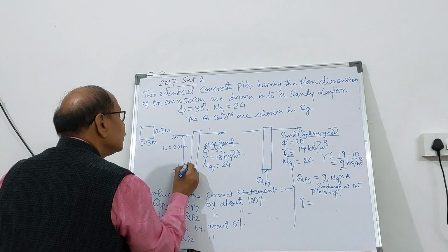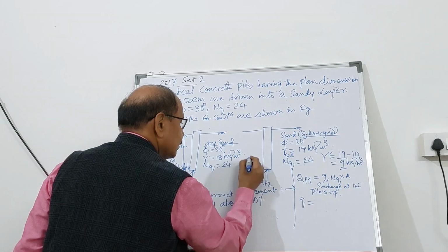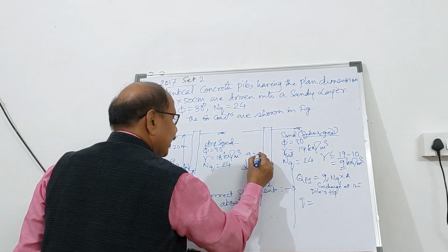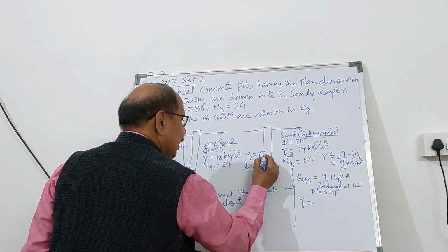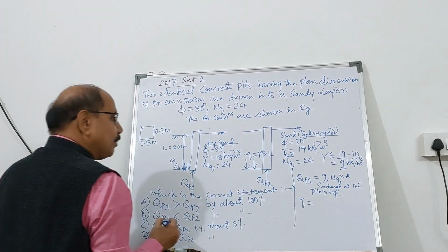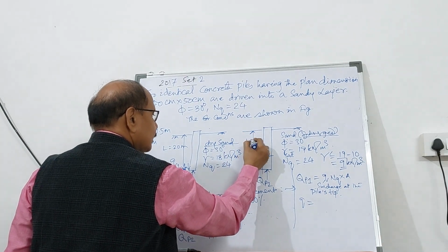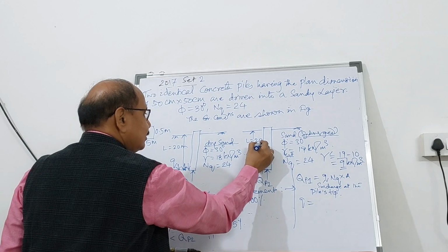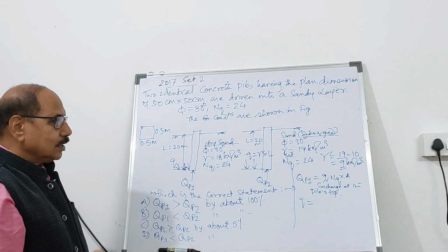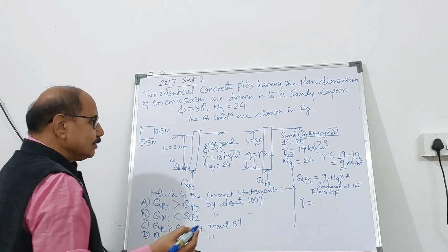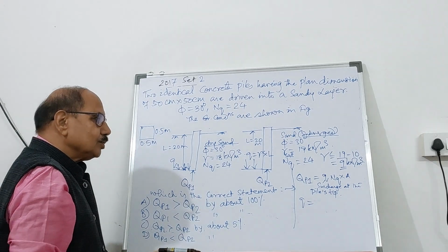Here, this is the surcharge. Here, this is the surcharge. This Q will be, because of submerged condition, gamma prime into length of the pile. Length of the pile here also is 20 because it is identical. So diameter and length are equal. Ground is also same, only thing it is dry and then during rainy season it got submerged.